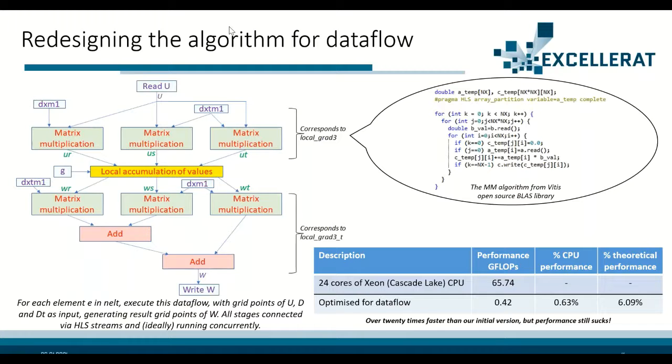Now, you can see at the bottom, we're nowhere near that, but it's really saying, from the perspective of the way I've designed the algorithm, if I could get the data streaming through and every single cycle productive and keep things flowing that data through, then actually that's the performance I should be expecting to aim for. And the fact that I'm so far off it, 6% of that, really illustrates that there is a big bottleneck here which needs to be optimized.